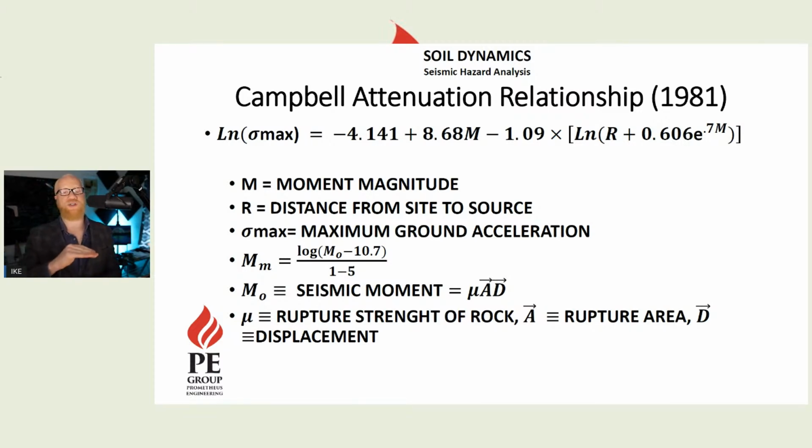And then when you get the ground acceleration, you're going to model on top of that your single degree of freedom structure with a particular frequency, and then you plot the spectral acceleration for that site relative to frequencies, okay? So we have several frequencies that we can model or build, which again are based on the mass and the stiffness. And then the frequency will affect the way that the structure responds. That makes sense, right? So I'm at this particular site. The floor shakes. Well, the structure will react based on its dynamic properties, one of which is its natural frequency or its natural period, right?